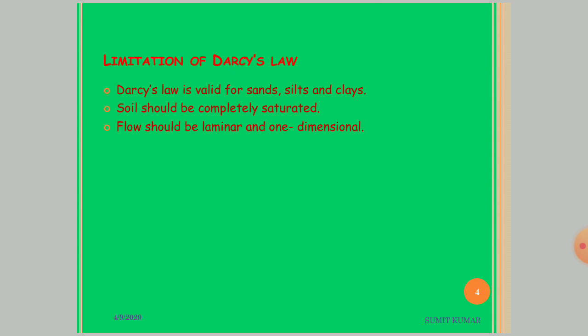Since the Darcy law is based primarily on Darcy's observation, there are some limitations of this law. This law is only valid for sands, silts, and clays, and this law is not applicable for gravel and other coarse material. For validation of this law, soil should be completely saturated and flow should be laminar and one-dimensional.